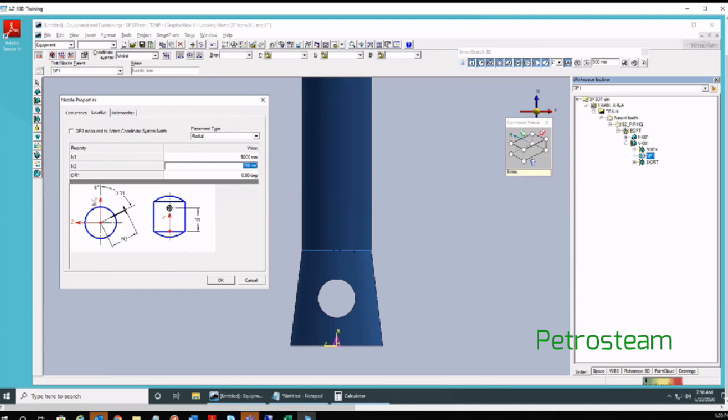Next is orientation. Orientation always take from north direction. Okay. In the plan view, this is your north. If I want the nozzle in the east direction, in the plan view, my orientation will be, this is your 0, up to east, it is 90 degree exactly. I have to input orientation 90 degree. Okay, enter. Whenever you key in any values, after that you have to enter.